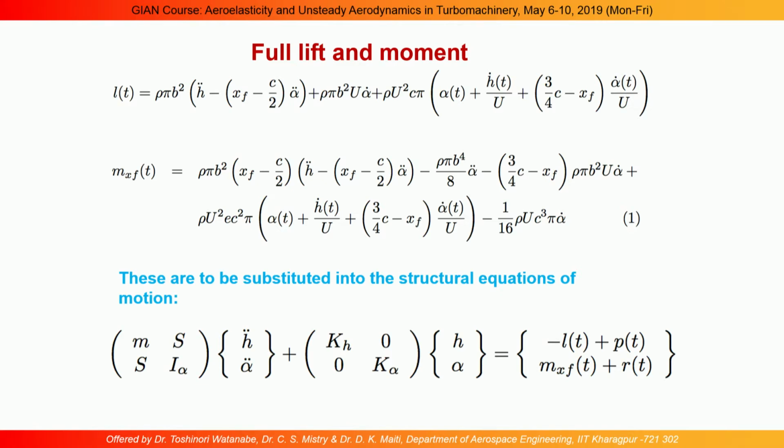So, this equation becomes something into right hand side equal to 0. That is why we call this system of equations a self excited system. Self excited system means the aerodynamic load that is developed is not an independent load. It is a function of deformation, a function of bending deformation and rotational deformation, and that is inducing the lift force and moments.